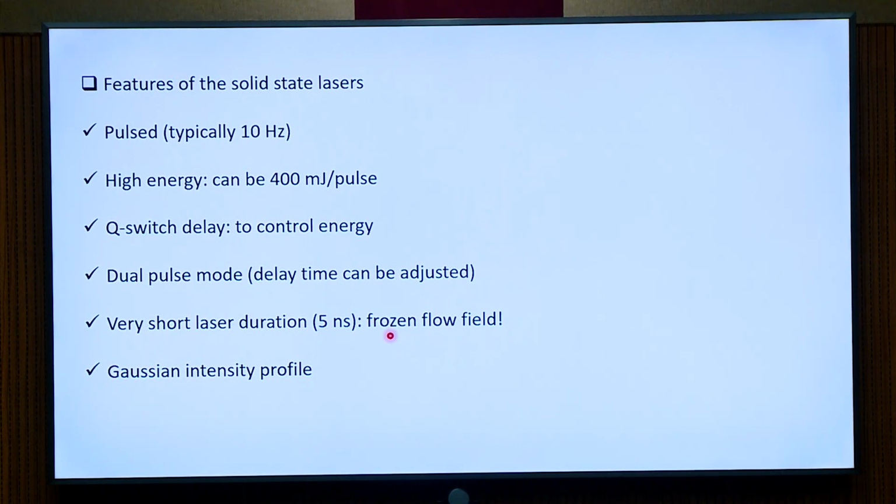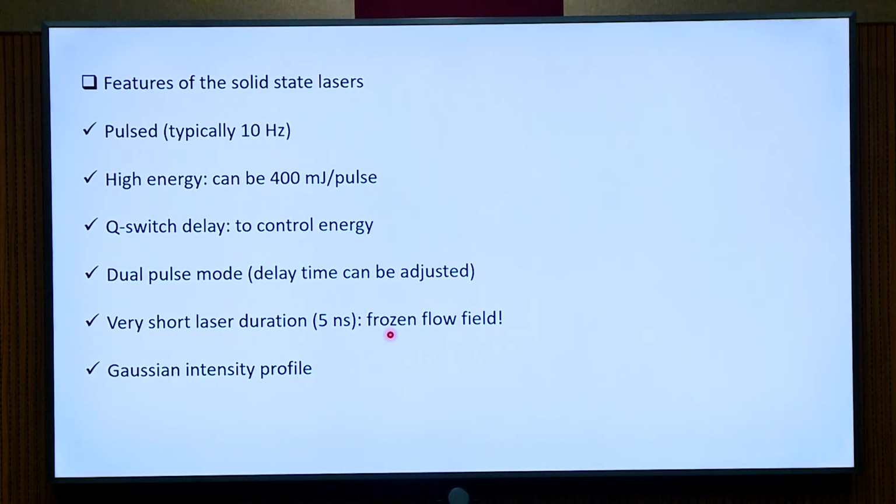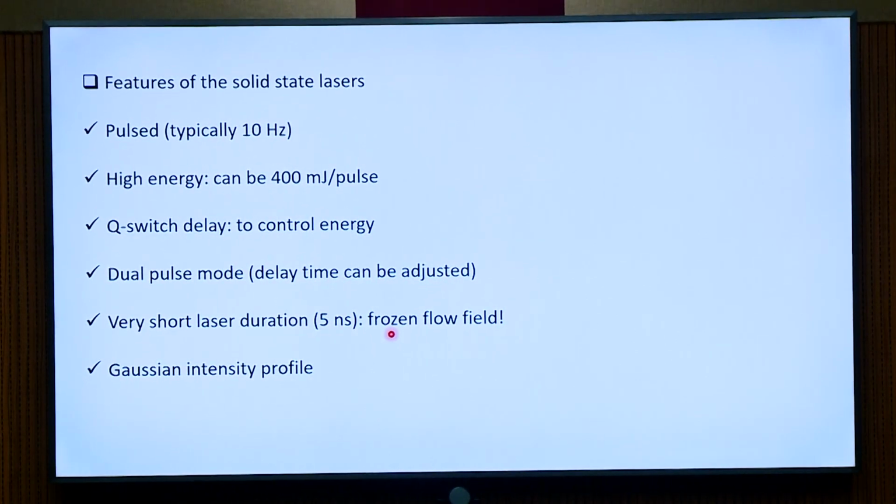Actually, there is nothing called an instantaneous time in an experiment, because the laser pulse has certain duration. So theoretically it is not instantaneous, but we can assume the image to be instantaneous if the pulse duration is much smaller than the time scale of the flow. Typically that is the case because this sort of time scale is not encountered in typical flows. I mean, the smallest scale is always larger than this laser duration.